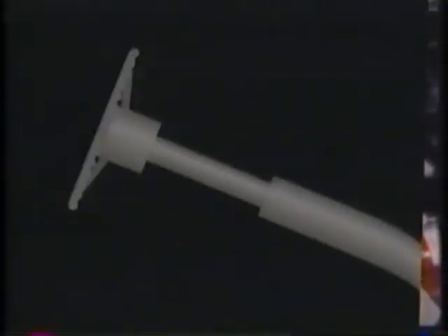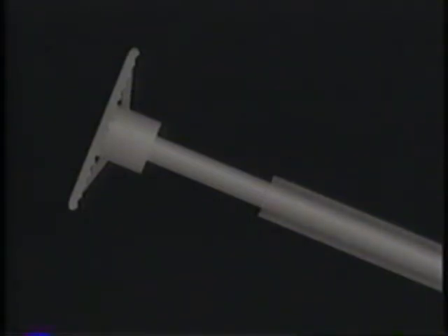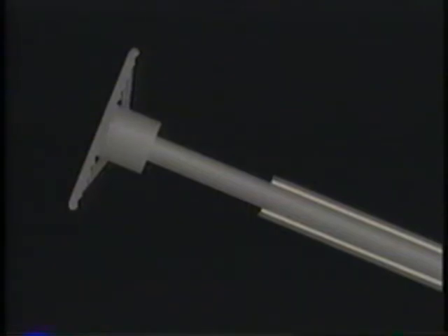Also, the system must be designed so that under crash conditions, the wheel stays in such a position so that it will strike the driver's chest and not move upward into the face area or downward into the abdomen. To achieve this, the steering shaft is generally made of 2 tubes, one placed inside the other. Plastic is injected between the 2 sections to lock them together. Upon severe impact to the steering wheel, the plastic shears and the 2 sections telescope inward, thereby absorbing the impact. Similar telescoping characteristics are built into other components in the steering column.